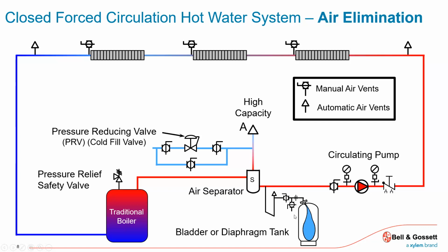Now we're using some type of expansion bladder diaphragm tank that does have a butyl diaphragm, butyl rubber. So we isolate, we separate air from system water through this diaphragm. So now I don't need to control it. I want to get rid of it. I already got my pocket of air that's going to provide the pressure reference point, expansion, all the benefits that we want.